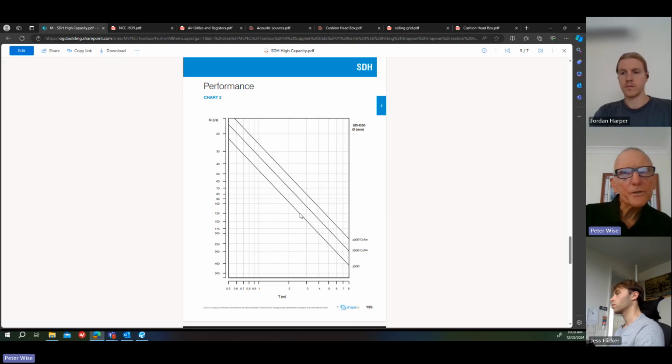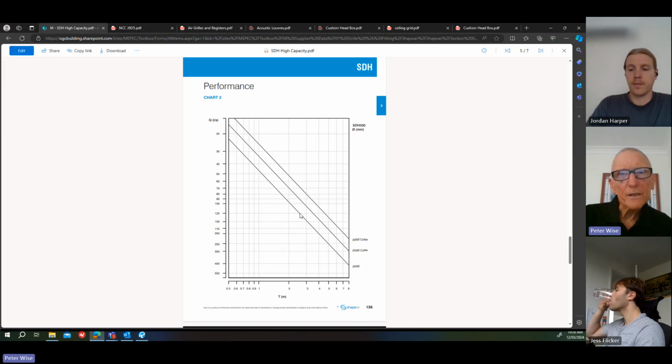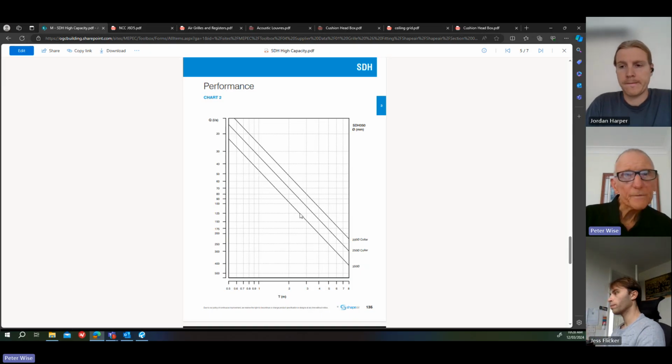If you do a high-rise commercial job, high-rise office, it's not uncommon for them to want to test the diffusers. So they'll go to a laboratory like we used to use Vipac. I presume they're still around. They have testing rooms where they can test the throw, the noise, all of those things, and determine whether it's going to do the job.